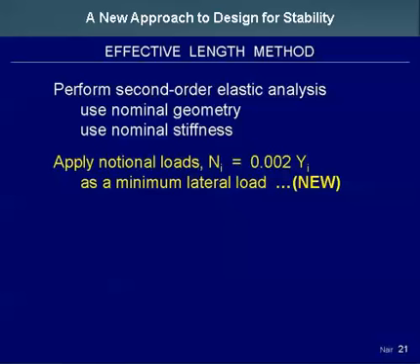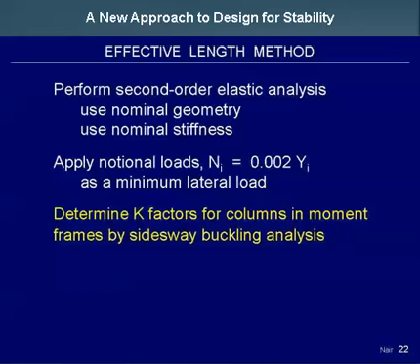But again, this will usually apply only when there's no applied lateral load, because this is a minimum lateral load that you need in all your load combinations. So in combination with wind, the wind load will usually be bigger than this, so you can ignore it in wind load combinations.